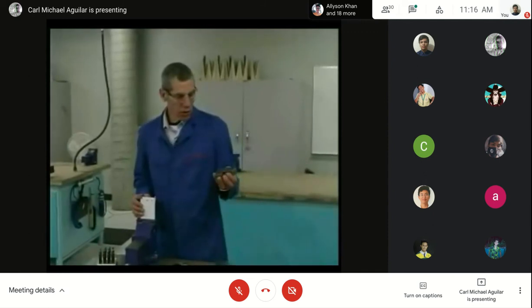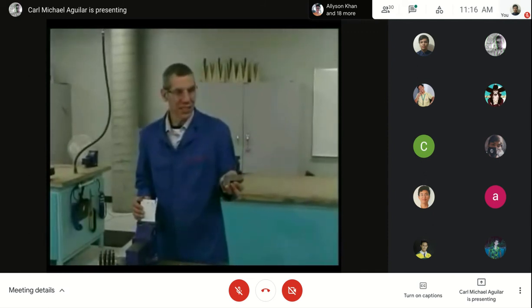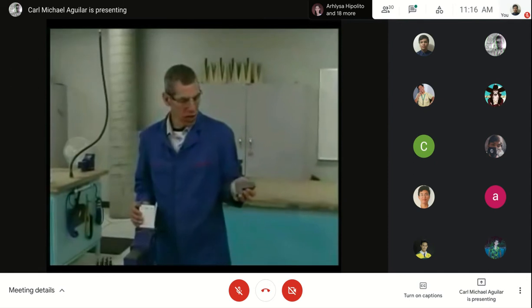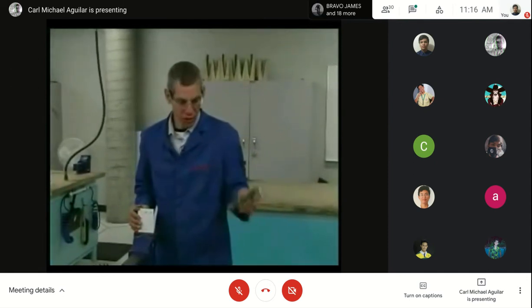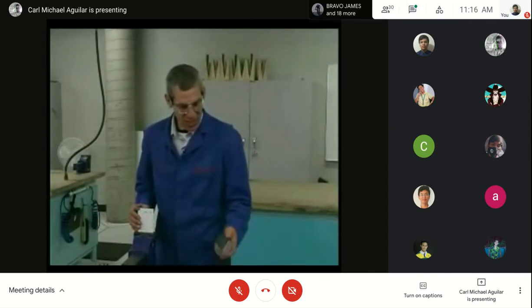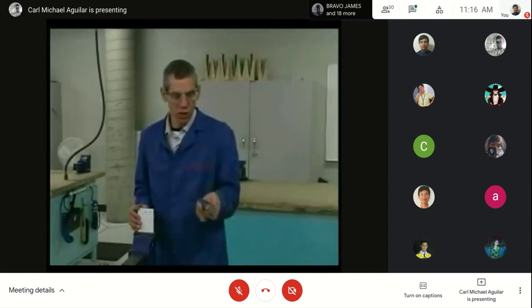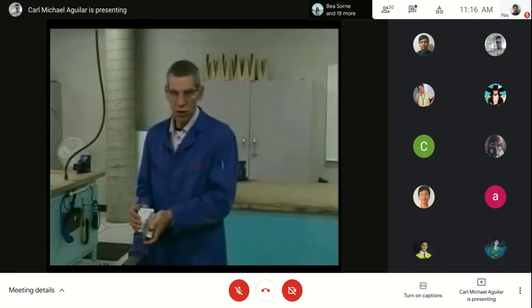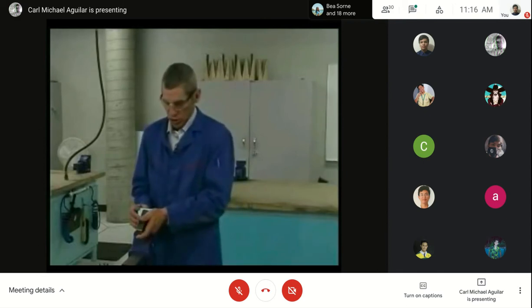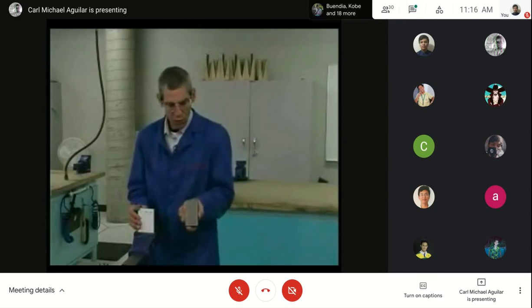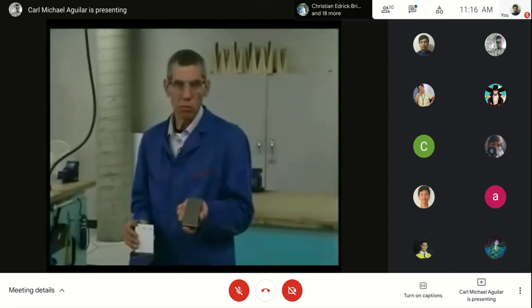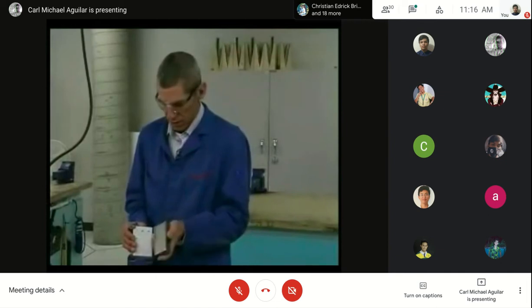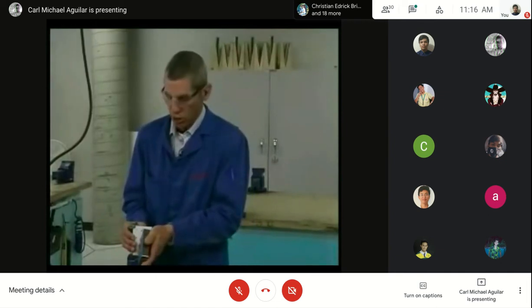Bucking bars come in different weights and different shapes. You can have light bucking bars that are various shapes and sizes. You want to pick one that's comfortable in your hand and that will fit the application on which you are riveting. For our purposes here, I'm going to select a nice heavy rectangular bar that fits in my hand and that I can easily control onto the coupon area where I'm working.